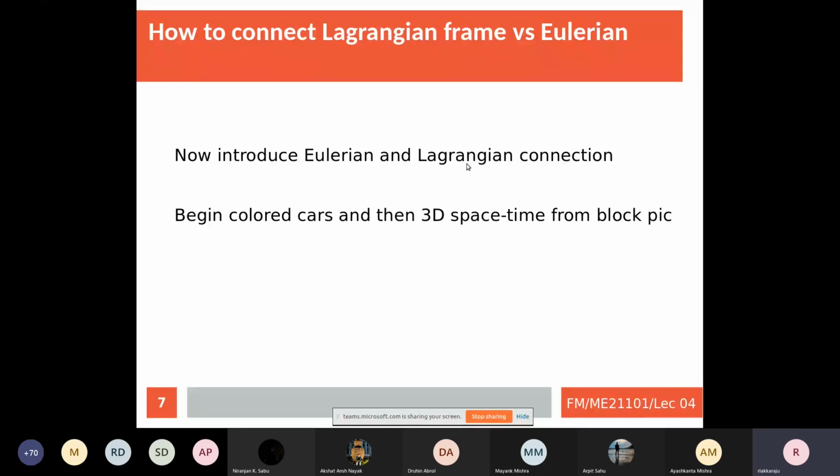And why does aerodynamics matter? Because the spoilers are used to basically push down the vehicle. At that speed, the vehicle might fly off. So the spoiler is used so that it can properly press on the ground and give a sufficient normal force for the friction to act. I see. But where do you find the spoilers, at the front or back? On the back. But why should I care about the back? Why can't it be on top, or perhaps the front, or somewhere, or maybe on the sides?